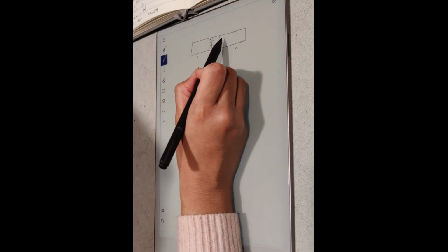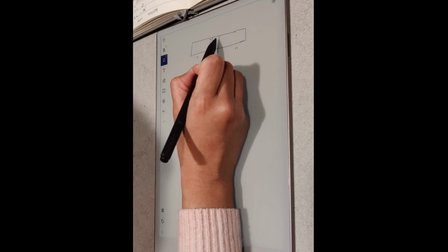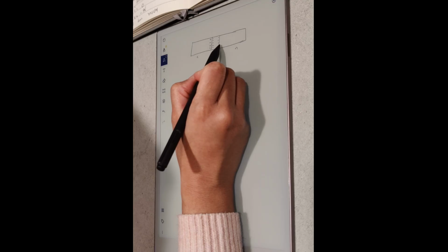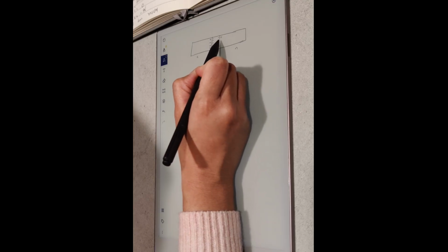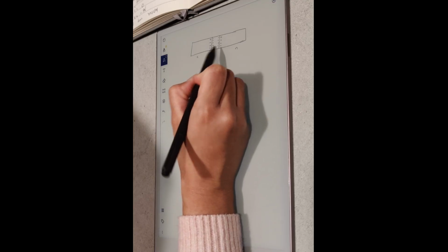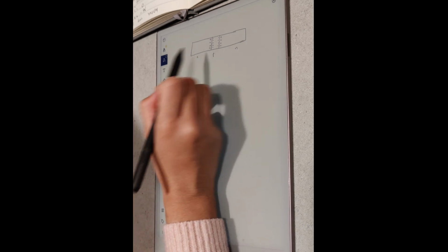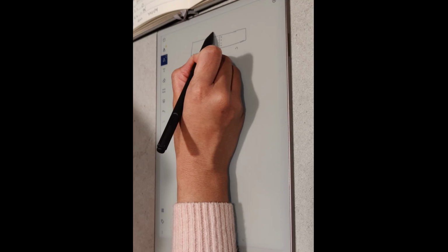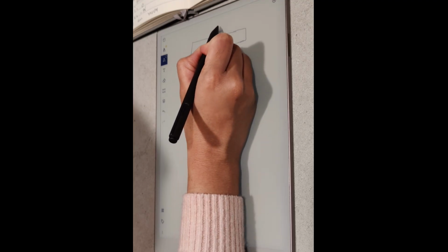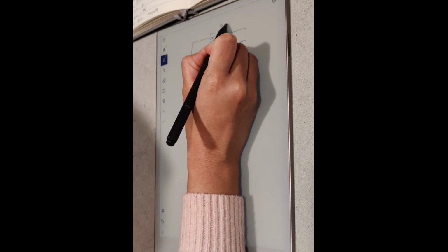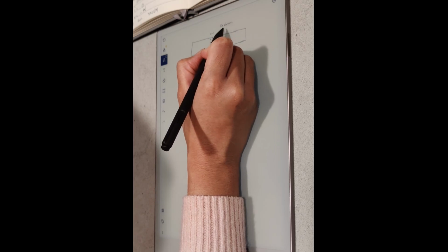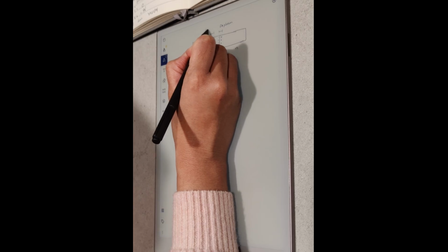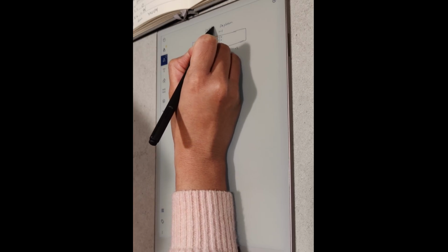Electrons are going to move from here to here, so this is going to have a negative charge, and because electrons have moved, it created an empty space, which is a hole, and this becomes positively charged. So these two junctions are going to have a region that we call depletion region. Remember, in the case of a diode, there was one depletion region because we had only one junction. Here we have two because we have two junctions.